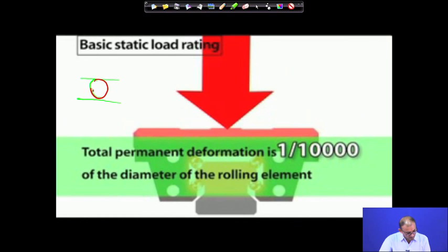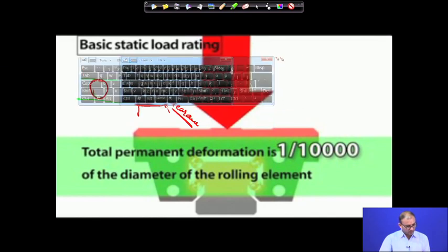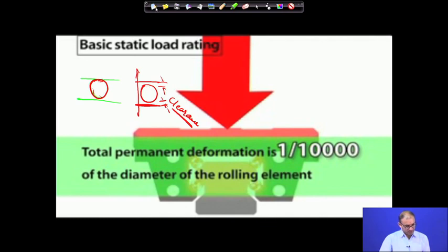Now if this ball deforms, it means there is some type of deformation, either it is not circular now or it has some worn component from any other location. So, now your ball will be something like this. It is not completely in contact with this part, so whatever part is there will create a clearance. This clearance will create a problem in the adjustment in this particular direction. When you are calculating the distance at one location it will not create a problem, but at this location it will create a problem.